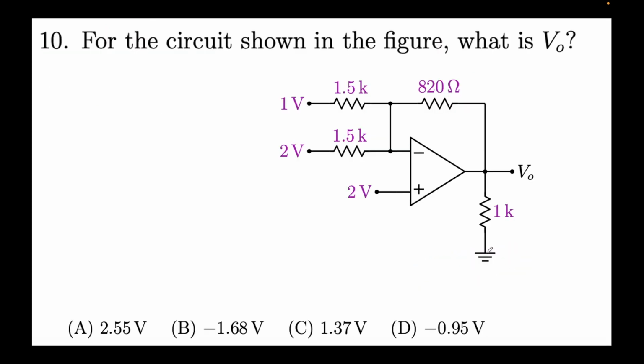Okay, so let's see if there is an option like that. Option A. Yeah, again a straightforward problem. This is actually the fourth problem in the same row, where we have provided two inputs. Effectively, this is not playing any role, because this potential is the same, so only the current flowing through the top branch matters. Your non-inverting terminal is sitting at a higher potential as compared to the inverting terminal. The 1 volt is driving the current. That's why you see a positive voltage over here, right?